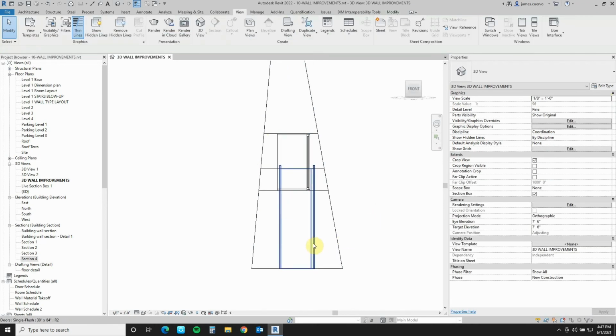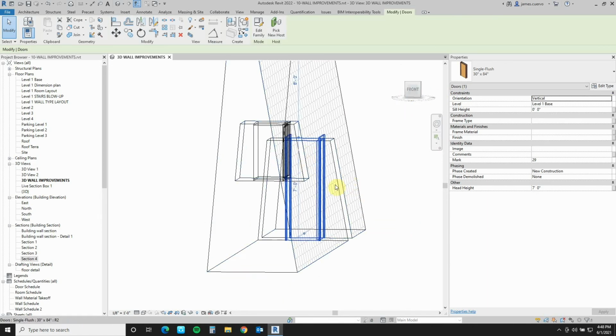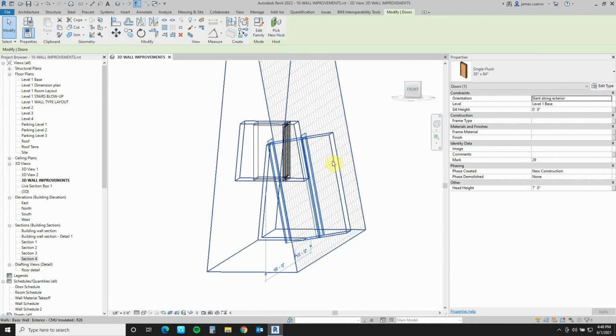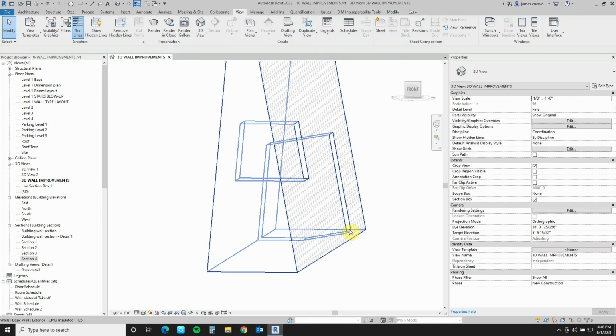Now, in the walls, it's a little bit tricky because the thickness here is going to have a direct effect on whether it cuts the opening or not. If these angles are too pronounced, then this door is not going to cut through the whole wall. So you have to be careful as to the angles that you have for interior and exterior, because I can actually do the same thing to the interior wall, to the doors embedded in this wall. You see what happens. I'm going to go ahead and turn it back temporarily, like for a hidden wall, and see what happens. It's raised now. You see that?